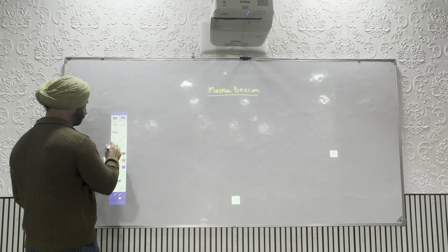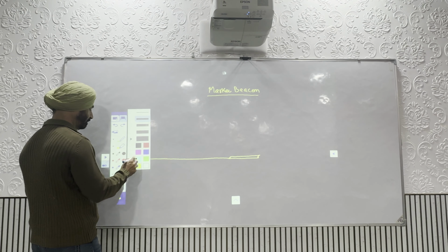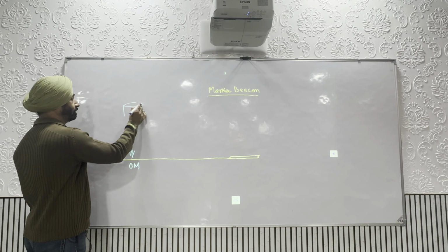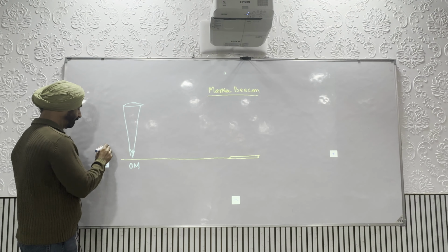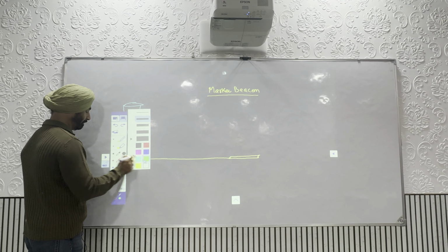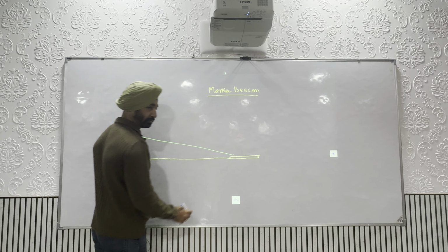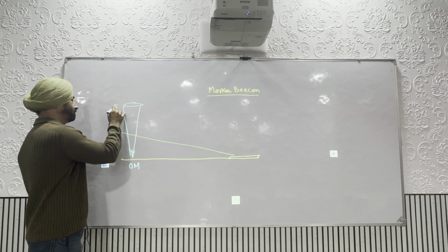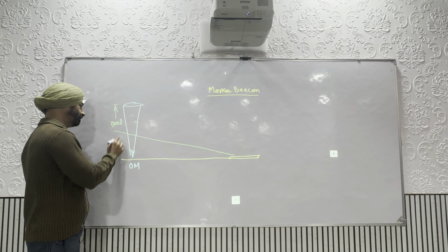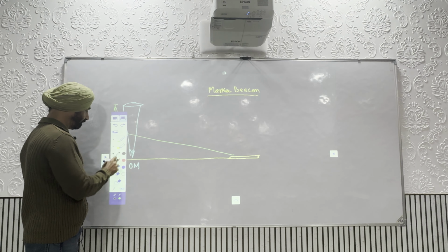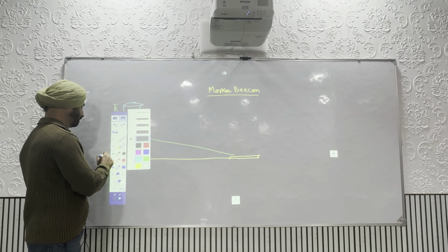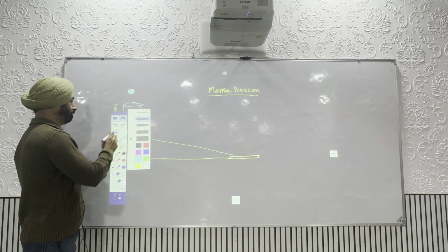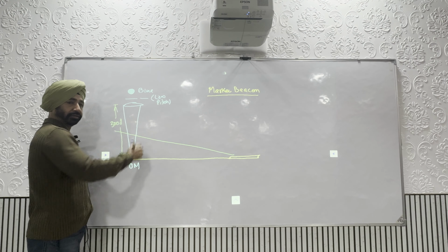So what are these marker beacons? These marker beacons are referred to as the outer marker, OM. Obviously, they are not too powerful, because you want the aircraft to receive signals only when it is on the approach path. Normally they transmit roughly about 3000 feet above the ground. When the aircraft comes over the outer marker, you have seen you have a blue light and you hear a low pitch audio of 2 dashes.